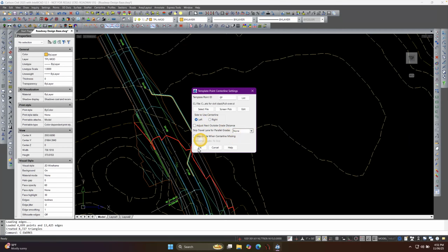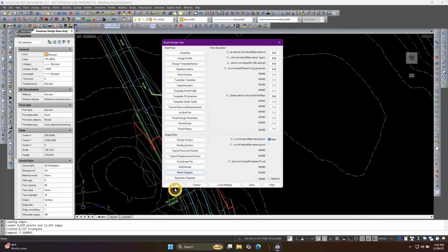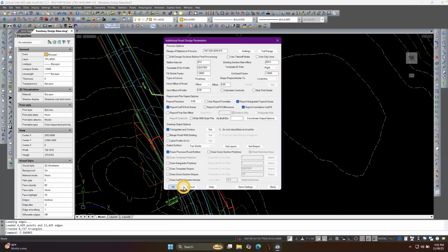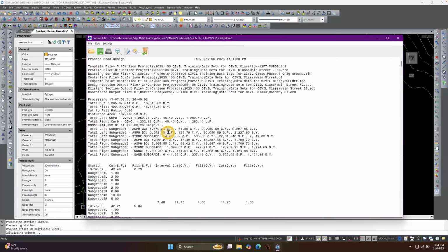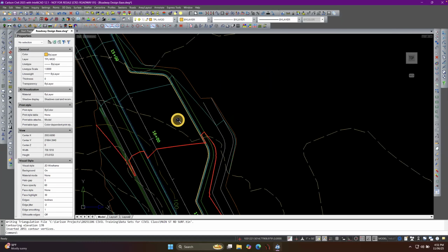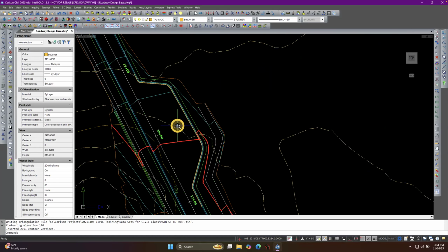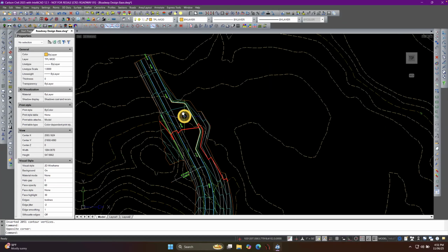Leave it at that, and that then should go from the crown of the road up to meet that. Well, right now there's no profile there, so I took the profile off, remember? So that was another thing that was possibly missing. So that's now put everything back and push this out at this 2% grade, okay?